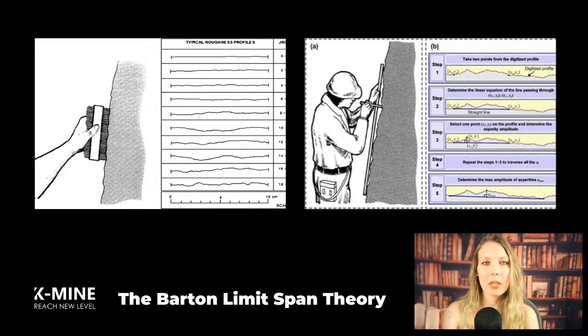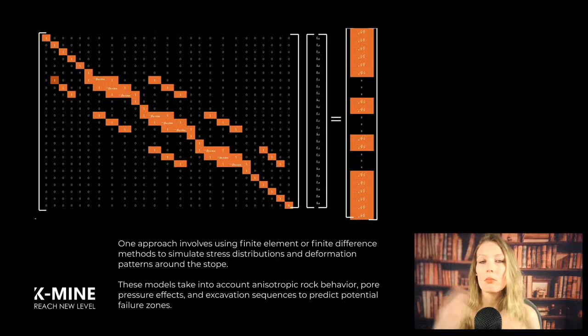For deposits with highly variable geological conditions, numerical modeling techniques provide a more precise means of stope optimization. One approach involves using finite element or finite difference methods to simulate stress distribution and deformation patterns around the stope. These models take into account anisotropic rock behavior, pore pressure effects, and excavation sequences to predict potential failure zones.